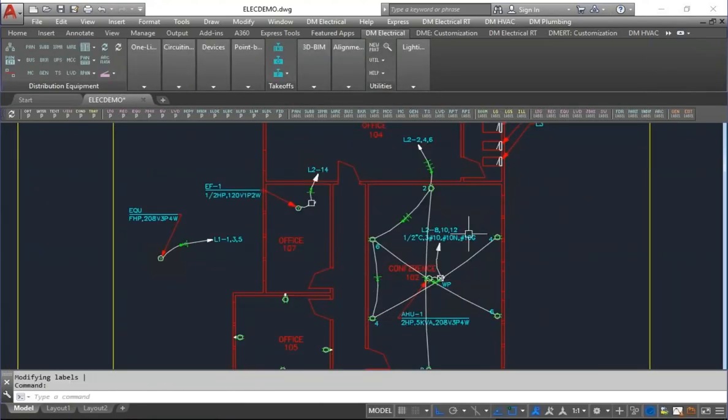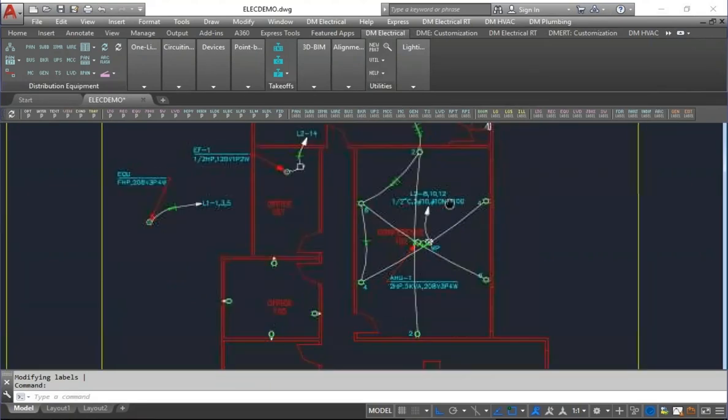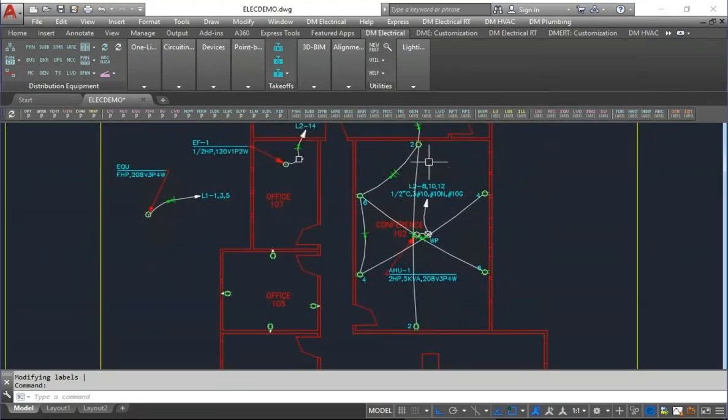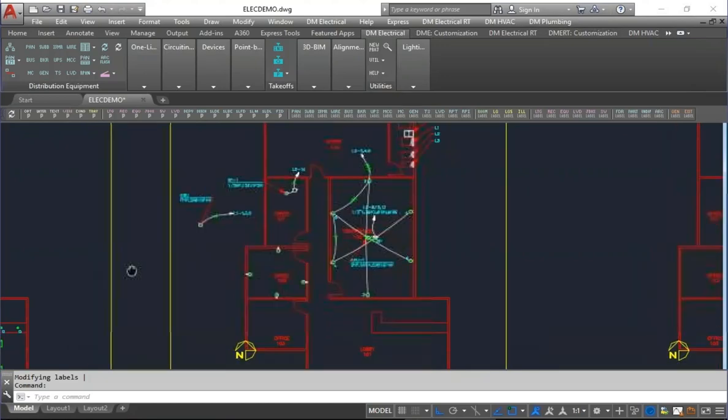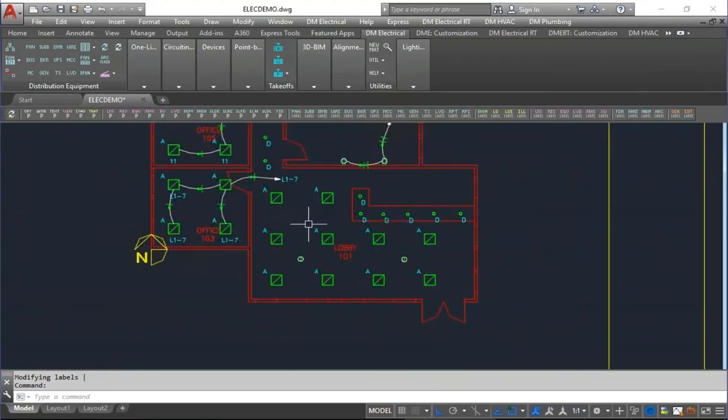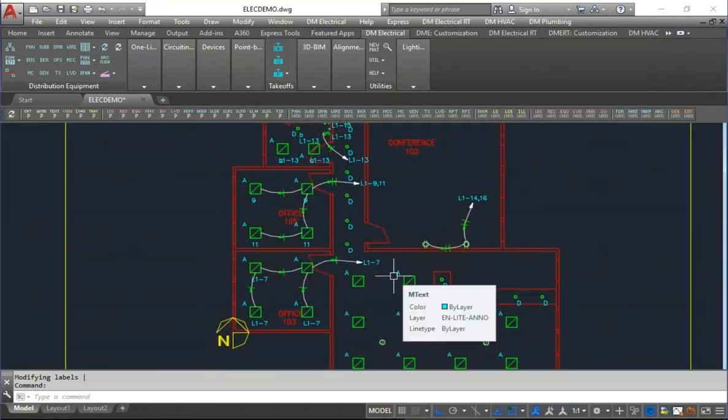So obviously this is not ideal for this particular configuration, but this is why we give the option. So we've got circuit 2, it connected those, got circuit 4, we connected those, circuit 6, we connected those, and then once it had all of that, it said, okay, we'll do for circuit 4, we'll connect it here, and for the rest of the stuff, we'll make this connection. So that's what it was doing. It comes into play more for light fixtures, where you might want to make sure that you connect within your circuit first before you connect to other ones.